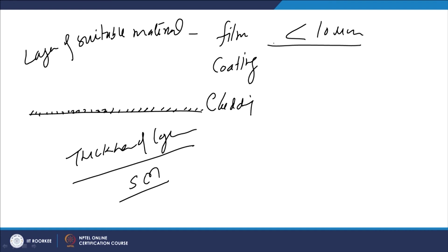Like PVD, CVD and very hard coatings, DLC like diamond like coatings are applied in form of films which are very thin. Then the coatings are slightly thicker and they are applied in the range of like say 10 to 1000 micrometer thickness, and for further greater thicknesses the claddings are used, like greater than 1000 micrometer.